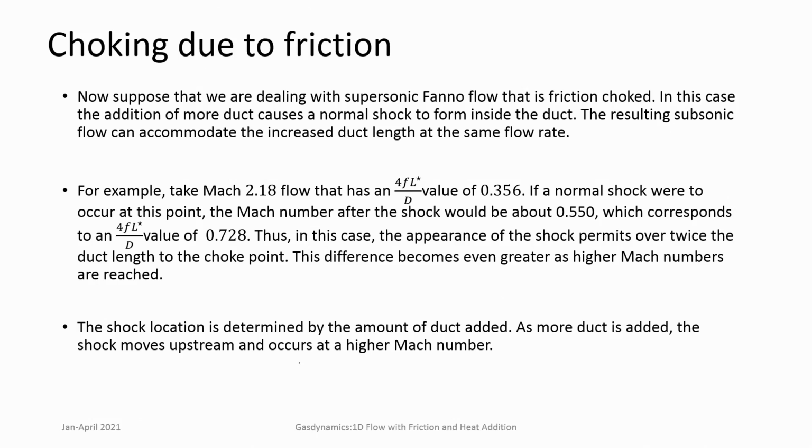And now you see what happens if the initial flow inside is supersonic and you get a choked flow at the end of the duct. How can you look at this particular problem? In supersonic flows, you have another medium or another solution which can help in this matter. What is that? That is the shock. Okay, because you have this sort of condition.